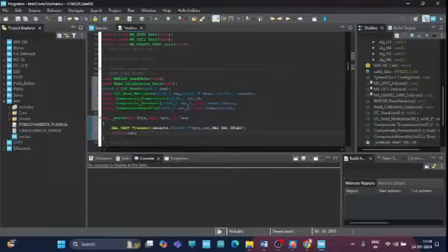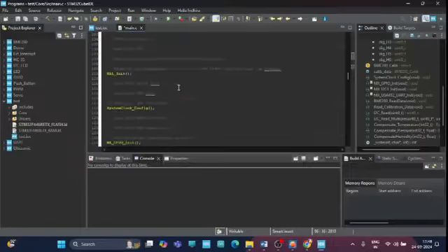Okay, so this write function redirects the output of printf to the UART. So it sends the string or data through UART2 using that HAL_UART_Transmit function, allowing the output to be viewed on a serial terminal like PuTTY. Okay, and then we can go for the main function inside.